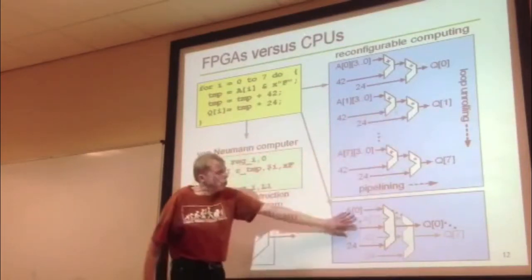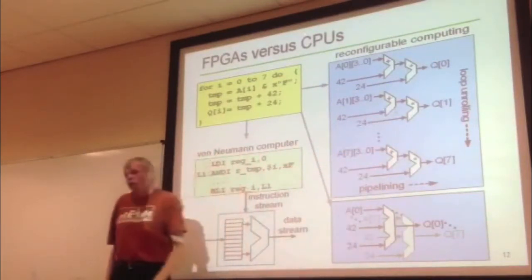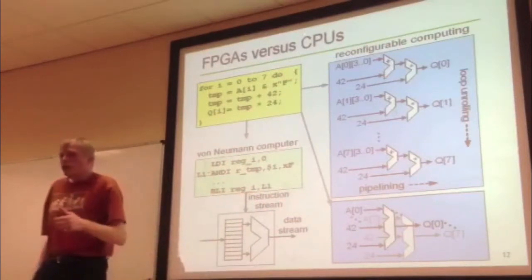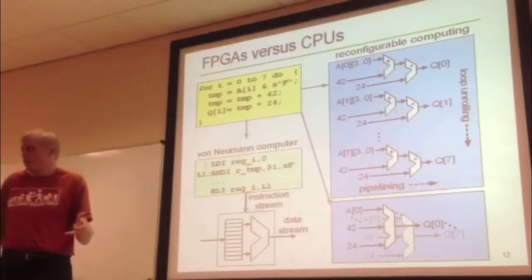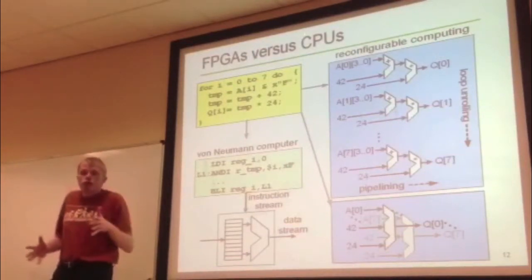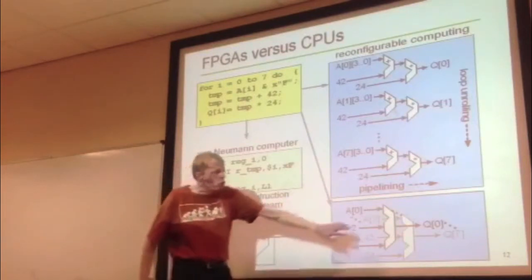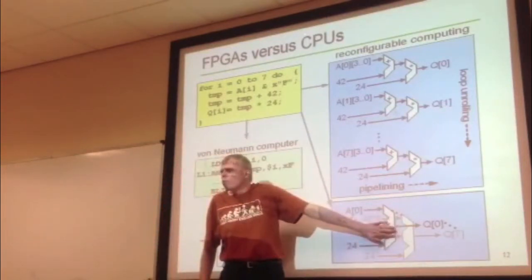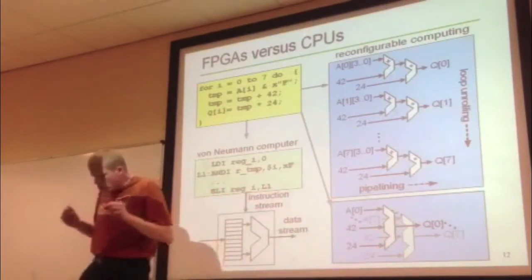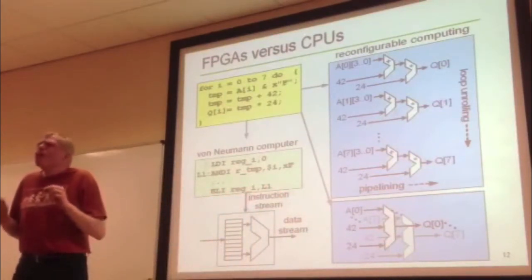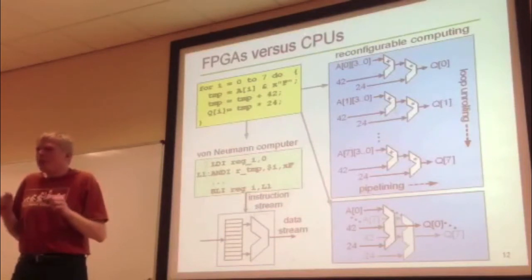If you want, you can also build dedicated instructions. Nobody tells you that an instruction necessarily is only addition or multiplication. You can have a multiply-add. You can do this. It's not necessarily good. It's a trade-off, because the more work you do, the slower this block might become. So in other words, programming an FPGA is a little bit more engineering than classical programming.